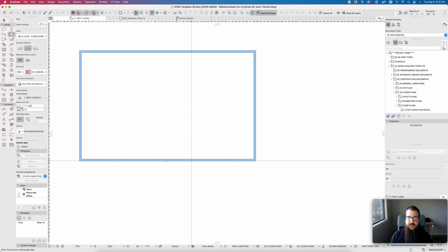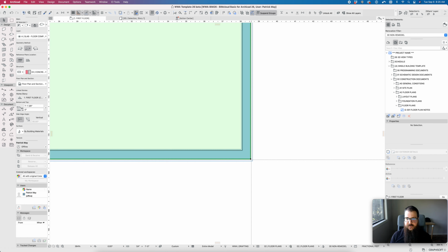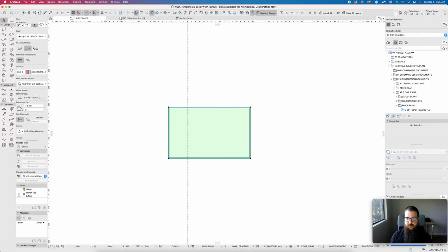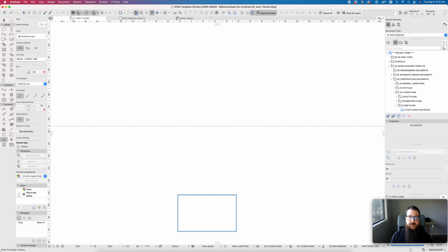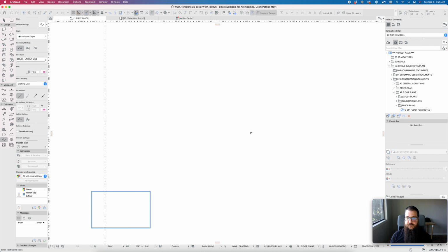Additionally, if you have geometry already placed, in the case of these walls, for example, you can hold space and that activates the magic wand and click on the reference line of that slab, or sorry, of those walls, and it will automatically place it to that reference line. That's particularly useful if you're using slabs to model things like paths and roadways and things that need to have tangential curves, and the spline is really the best tool, the ideal tool at making those tangential curves.